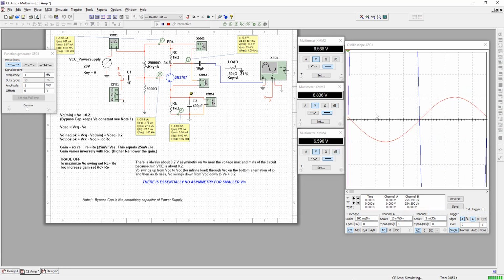The blue traces my output. So we see the effect is true. We're going to have a large increase in our input. I'm going to show you the scope of this. I have to increase my scale to 200 millivolts per division to capture the top and bottom. And notice something else that happened though. We have a 180-degree phase shift here. Let's remember what it was before.